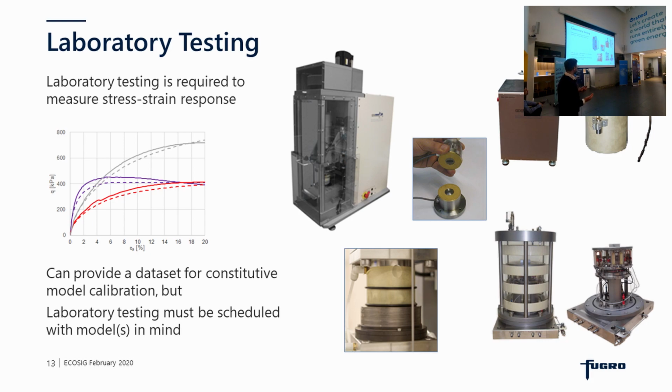So how do we go about generating the right data set to adequately parameterize a constitutive model? Now, laboratory testing offers a way for us to measure soil stress-strain response in the laboratory, which is often not possible to do in situ.